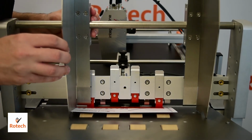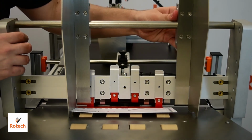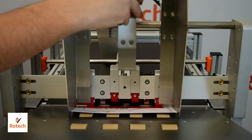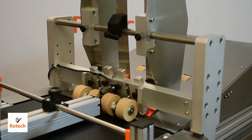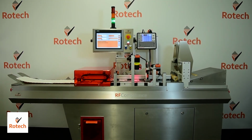Then we can adjust these hopper plates in by loosening the handle on the back of those. And then once they're in place on the side of the product, simply tighten them back in place. Then we can get the center guide, simply slot that over the bar and lock it in place with the handle on the back. You should now be able to operate your RF compliance. For further guidance on how to use the machine, please contact Rotech support.